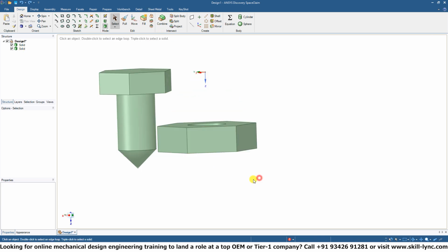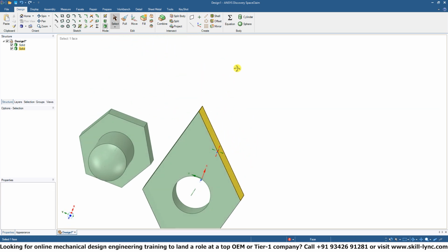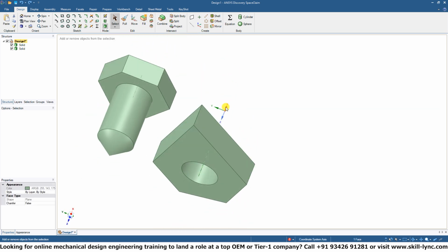Over here, let's say you're not happy with this surface. If you click fill, it tries to fill in the area or remove the feature in a logical way, or SpaceClaim tries to predict what you're doing. So how would you fill this area? You'd connect the left hand and the right hand edges, or you connect the top and the bottom edges, sort of a way. It tries to do it in the least obstructive way, right?